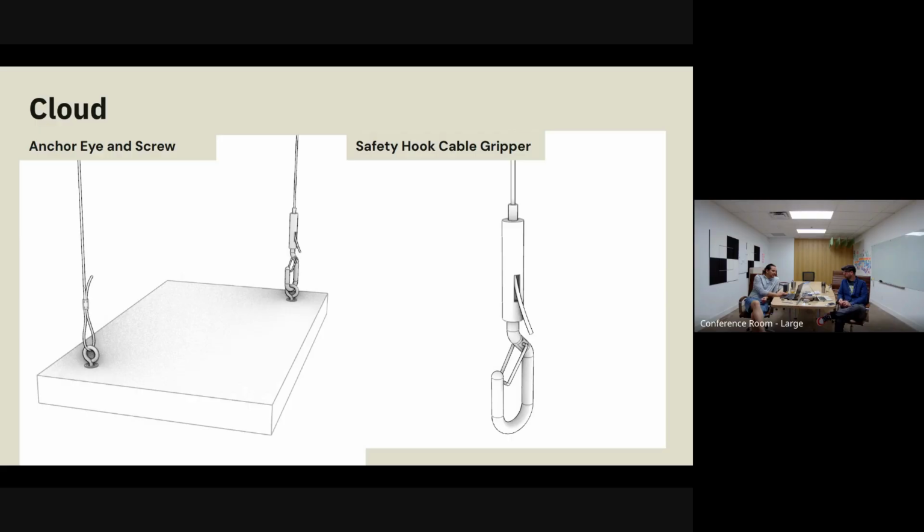Okay. Peel and stick. We're gonna stop presenting for a second. Peel and stick, the problem that you have with that is you truly need a clean and fresh surface. And when you tell people that it needs to be a level 4 or 5 finish drywall or high grade plywood that is face down, they hear level 4 or 5 finish or plywood. That's all they hear. And they don't go buy the high grade because that's expensive. They don't do a level 4 or 5 finish because that's expensive. And they don't always make sure that the plywood's face down.